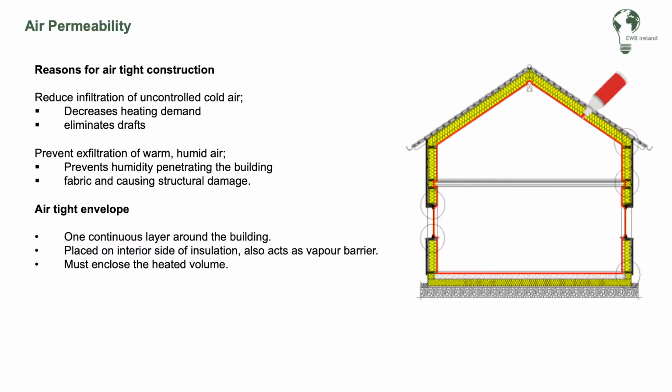And these are generally what you want to do. Floor to ceiling height of about 3 meters, narrow plan width, controlled solar gains, very important, and that thermal mass comes into that as well. And of course, where you position openings. It's an issue in cities. You get noise from traffic, you get fumes coming in, but it's a rule of thumb if anyone does decide to go that route.